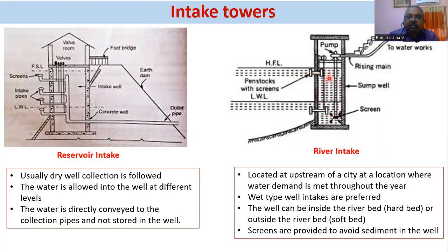Some is pumped to the water works, right? So this is located upstream of a city at a location where water demand is met throughout the year, right? So the well can be inside the riverbed if the riverbed is hard, outside the riverbed if it is a soft bed. It depends on that. Screens are provided to avoid sediment in the well.